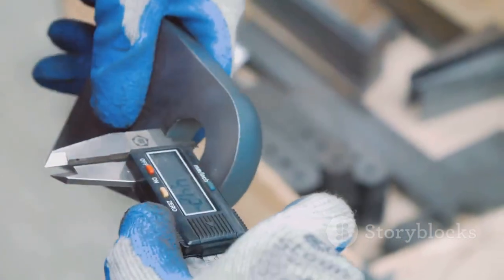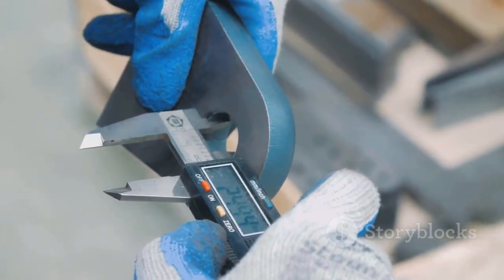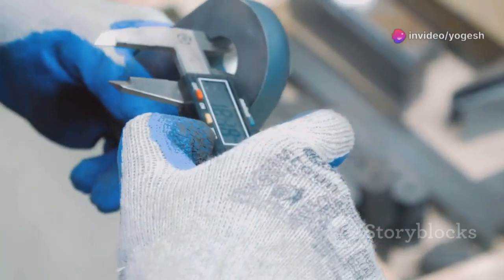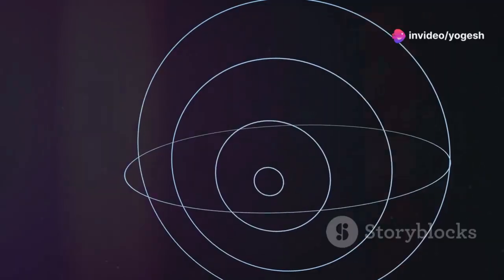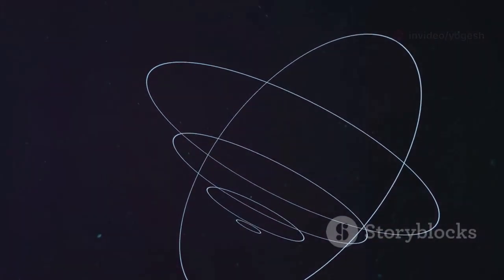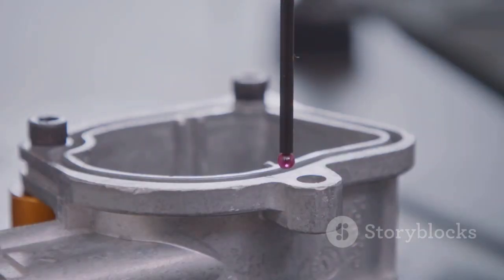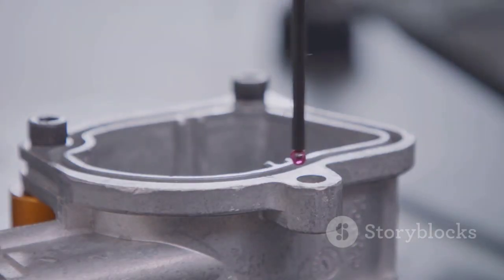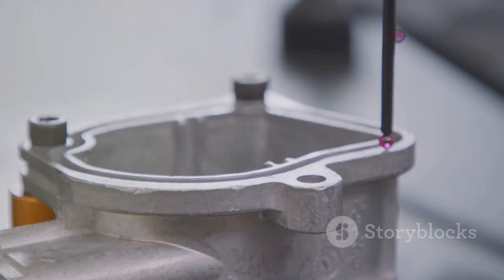Instead, engineers often use position tolerance, a simpler, more practical control. Position tolerance uses a different symbol and controls the axis directly, making inspection much easier. You can check it with simpler tools or a basic CMM program, saving time and money.